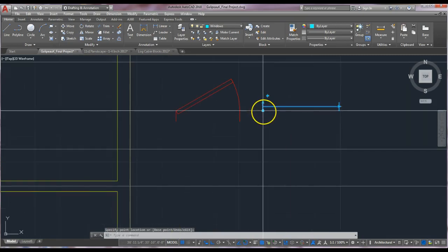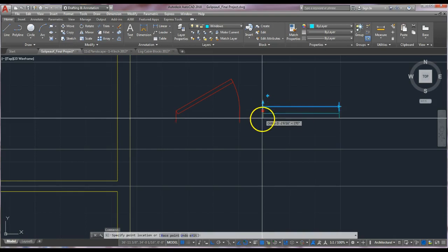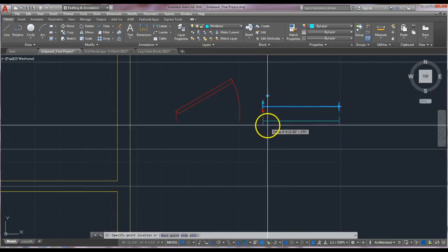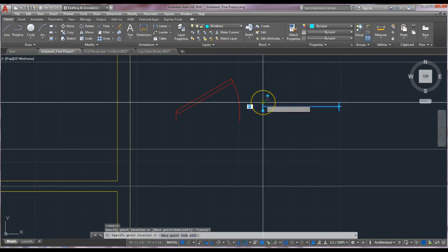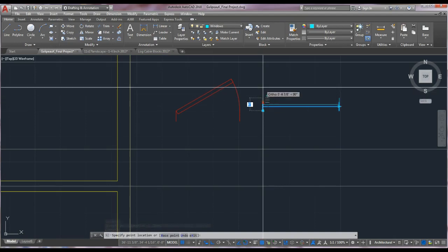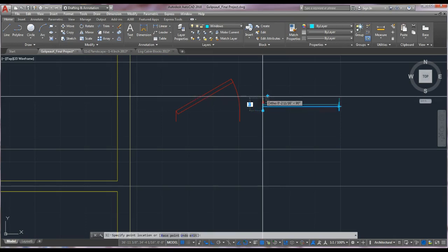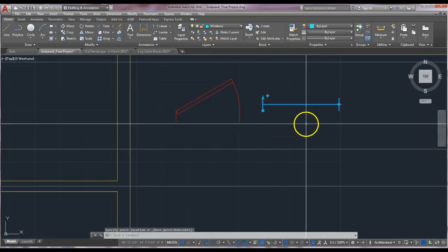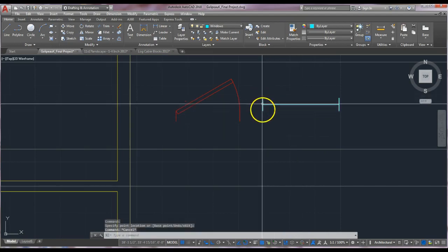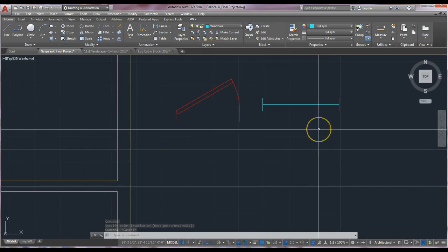The other thing that adjusts on the dynamic blocks is the size of the wall that it would sit in. If I select this, this is where I can move it from. But if I select this upper arrow, it tells me that it's already set up for a 4-inch wall. If I drag it up, I can go from 6 to 5 to 4. Now I need 6-inch walls, so I'm going to drag this up until it says 6 and click. If I hit escape, now you can see that the wall areas are set to the correct wall width that I'm using.